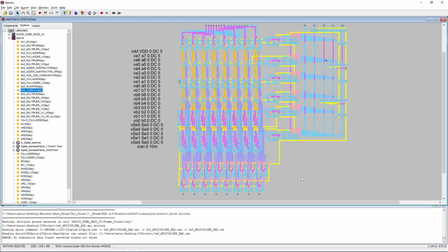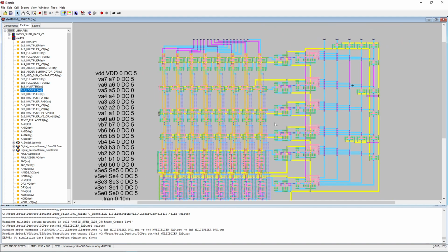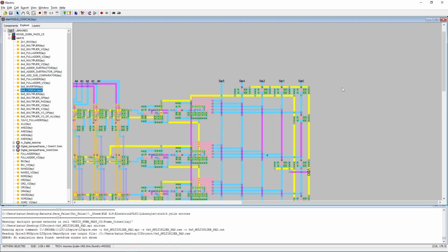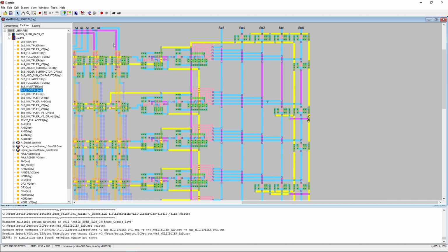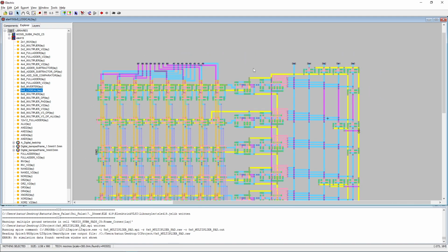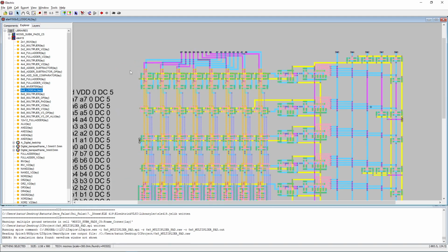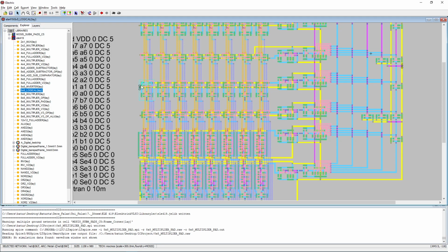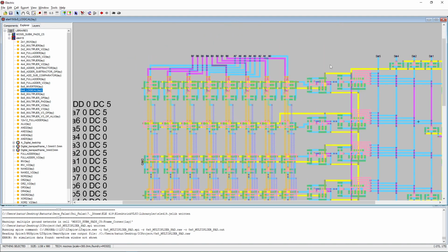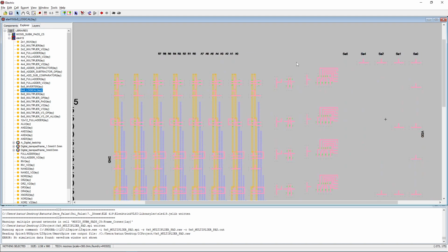The cabling here, I love it. I really put my time into it. Now there are 5 selection pins. The third selection pin is used as don't care. And the power saving I mentioned really shows itself here, because these arrays of ANDs, ORs, XORs, XNORs are just powered up by specific opcodes. If they didn't receive their opcode, they would not work and they would not consume power.